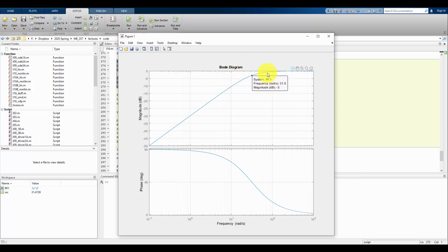And we have, once again, this roll off here. It doesn't immediately attenuate to negative infinity decibels. It has this decay as we go to the left, and we are not perfectly preserving things above the 5 Hertz. We have a little bit of attenuation happening, and then we level off near that 0 decibels.